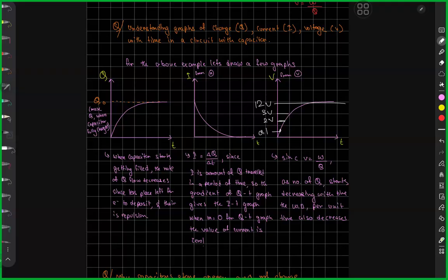So, do you see what's happening? On all the charge that has been accumulated, a different amount of work was done. If I have stored 10 coulomb of charge on one side of the capacitor's plate, all of these 10 coulomb of charge did not have 12 volt worth of work done on them. They had different amounts leading up to the last 1 coulomb having 12 volt of work done.